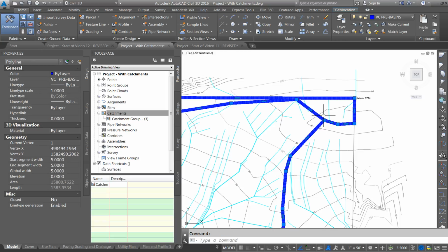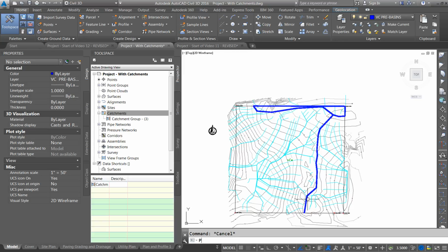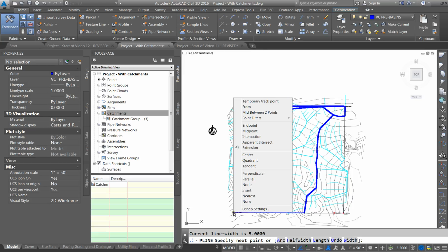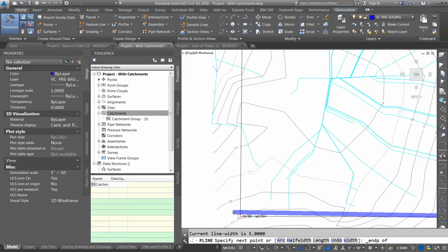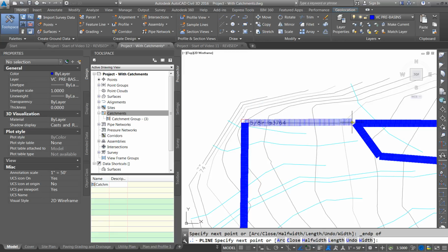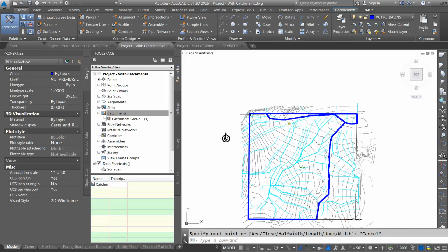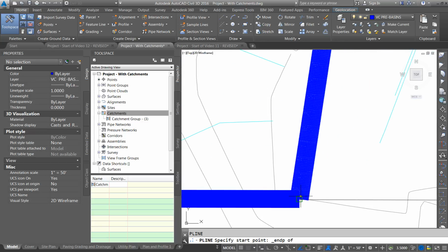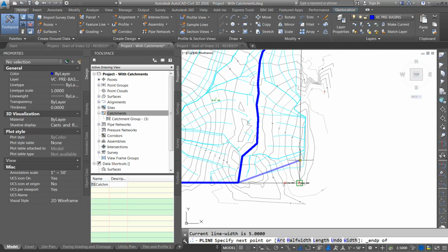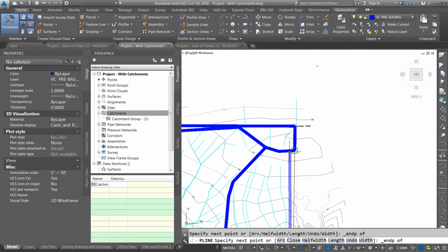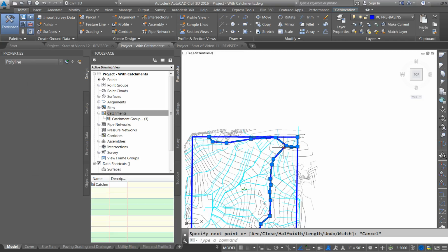Now, when we create our polylines, I'll show you 2 methods. Right now, I'm just drawing the boundary of my polylines, but I'll actually need to create a closed polyline in this. So I'll create the boundaries first so they're not overlapping. And then I'll do the last one through here. I'm just looking at my actual area. We would have to look at what's going off-site in addition to this. So, an endpoint up here. So we would need a closed polyline.